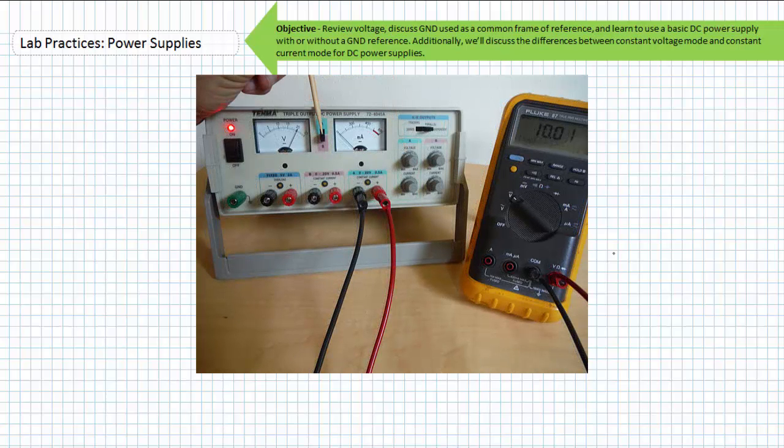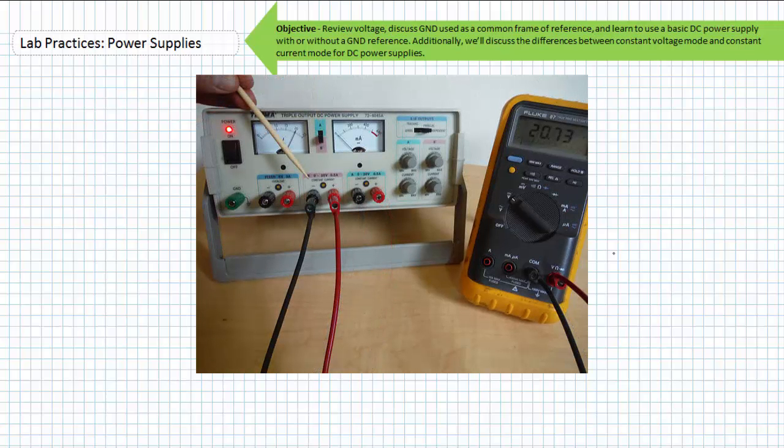If I accidentally had my display selector knob reading the B terminals, I might be tempted into believing a contradiction exists. The needle meter indicates something close to 20 volts, but the DMM in voltmeter mode is reading 10 volts. Obviously, I'm on the wrong set. I can measure the B pair using the DMM in voltmeter mode, and it shows 20.73 volts, resolving my contradiction.